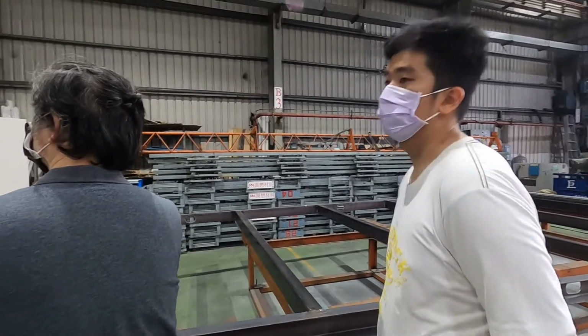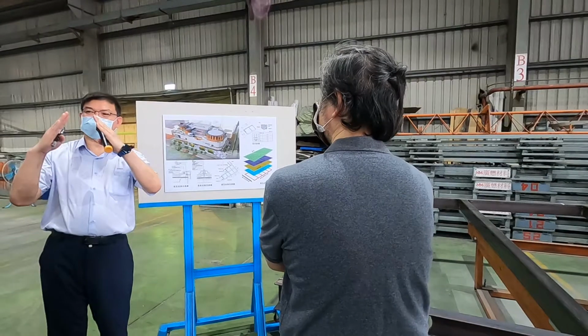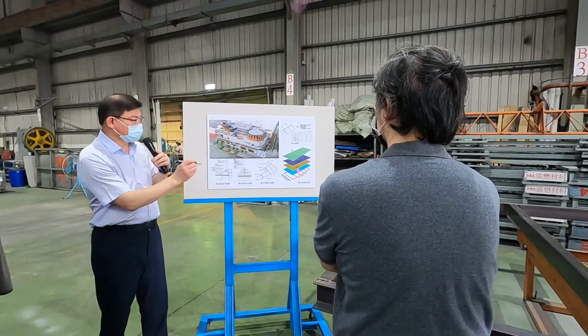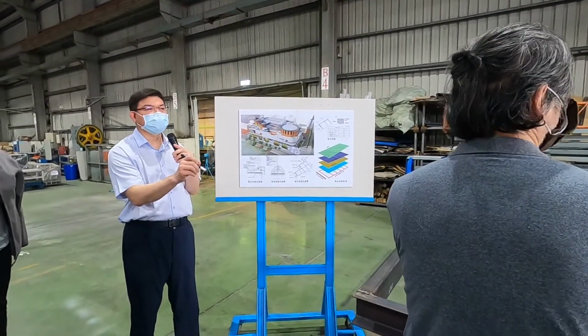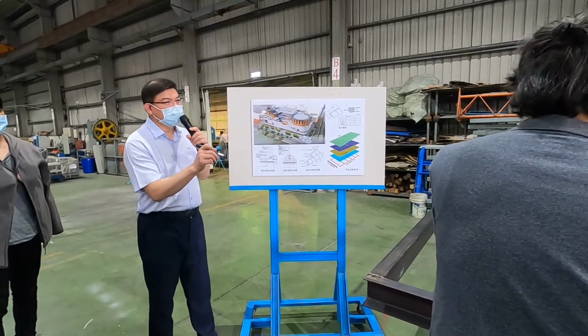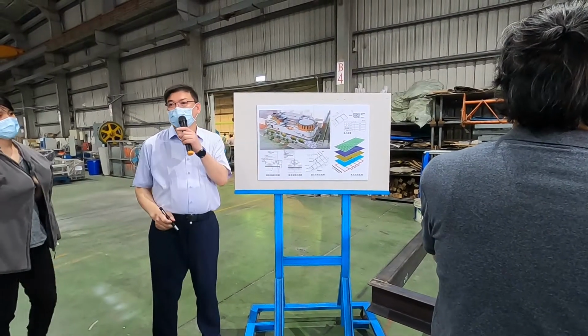I forgot how to say T shape. It's not a perfect rectangle, it's in this shape. A tapered shape, yeah. So that is the tapered framing, which is this one. And we are going to install the layers on top of the framing to make it unitized. Then we can deliver the whole unitized panel and install it to the roof in only 2 days.